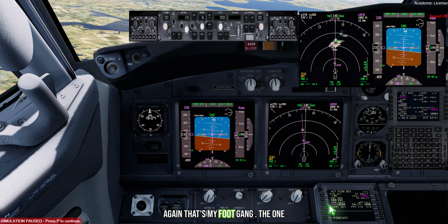Gang, the one thing that I want you to really get in the habit of, because it's so valuable, is that the flying pilot during an arrival and an approach should be almost continually up on this page. If for any reason you go out of it, come back to it and always be monitoring this information. This ought to be in the cross-check of your arrival and descent and approach profiles as much as you're watching information here and here.